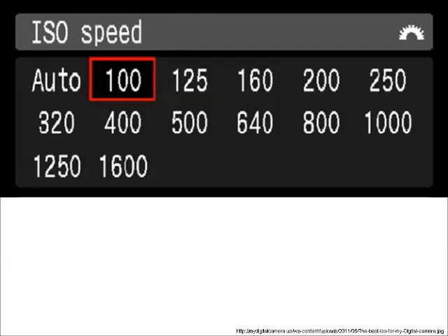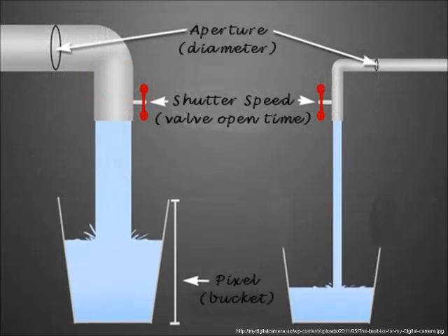Not to forget also then ISO, which amplifies our signal. Now just to stress a point here, ISO doesn't change the sensitivity of your sensor. Your sensor has a fixed sensitivity. All it does is amplify the signal, everything in your signal, including all of the noise as well.